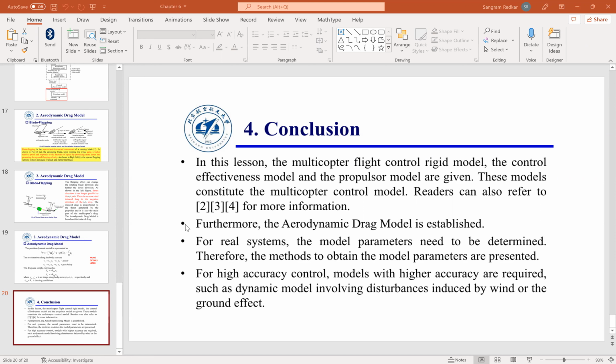This is dollars to pesos. You cannot equate dollars to pesos. You need to transform either the inertial velocity into the body velocity or the body velocity into the inertial velocity. And the way we do that is we have this rotation transformation, which I'm going to call this E to body, something like 0R1. So V1x, V1y, V1z is equal to V0x, V0y, V0z. Everyone understood this? The first equation, that motion equation, is nothing but the expanded version of this.